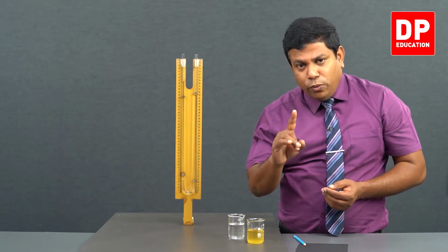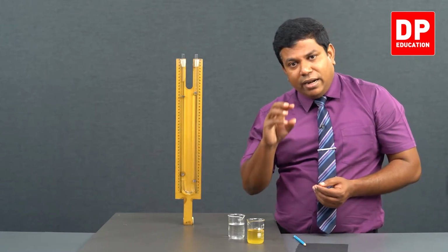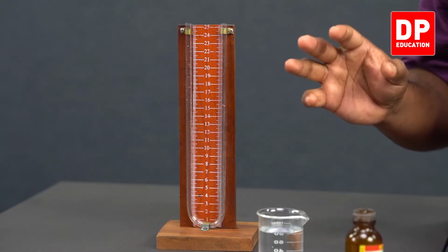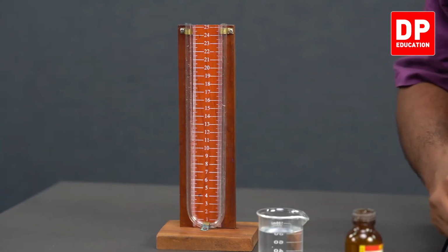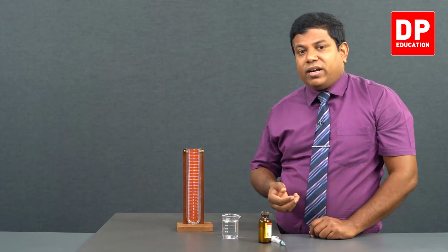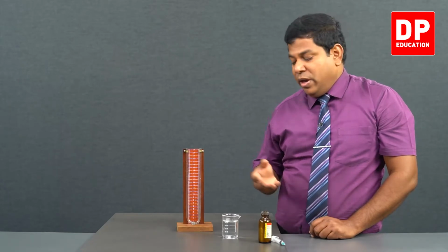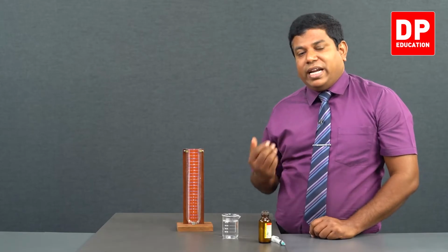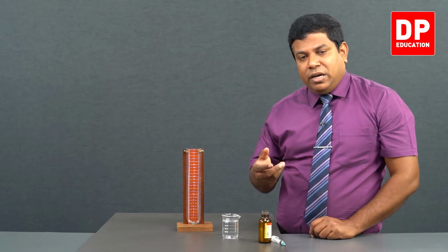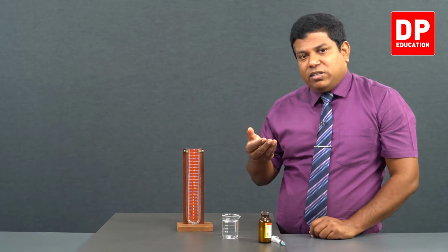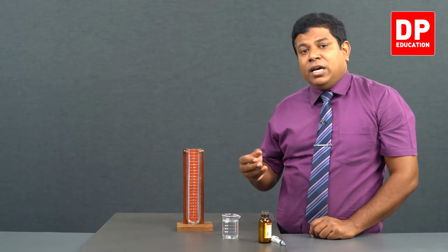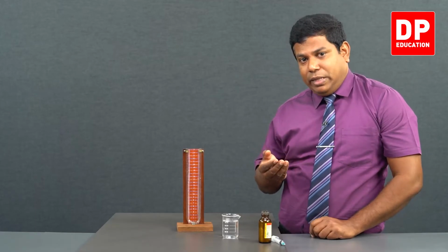Let me show that to you using another U-tube with mercury. Now I have taken another U-tube. Here I am going to show you what happens when we use water and mercury for this experiment. As I explained, mercury's density is 13,546 kilograms per cubic meter, where water's density is 1000. So the relative density of mercury is 13.546. Because of this, to raise the mercury level by 1 centimeter, you have to put a lot of water, around 13-14 centimeters of water. I am going to show you that here.